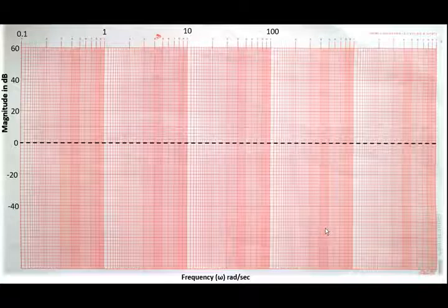And in the same way, in Bode plot, why we are studying this Bode plot, because here we can find out the marginal gain value, that is the magnitude value or angle value. These are the marginal values beyond which the system becomes unstable. So we are not leaving the system to go for instability.